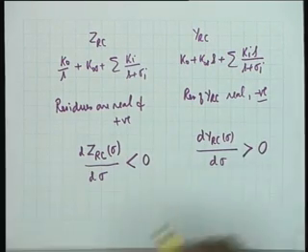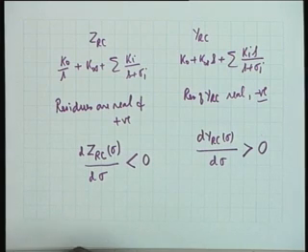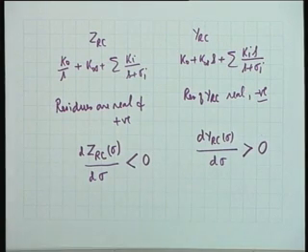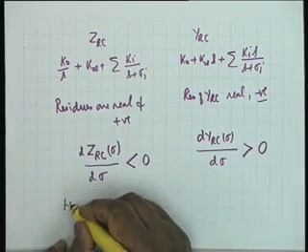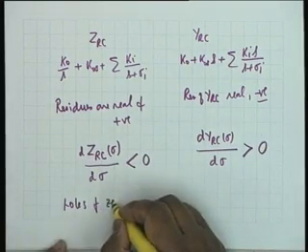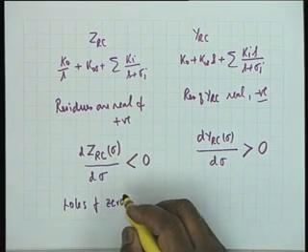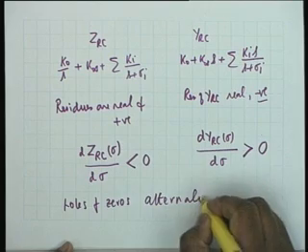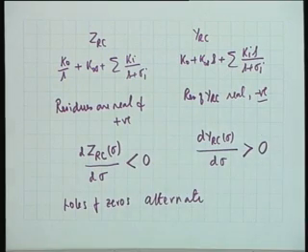And as a corollary to this property, that is, the slope is strictly monotonic, either strictly negative or strictly positive, it follows that poles and zeros in either case have to alternate. There is no other way. Poles and zeros alternate. This is a consequence of this slope property. They have to alternate.